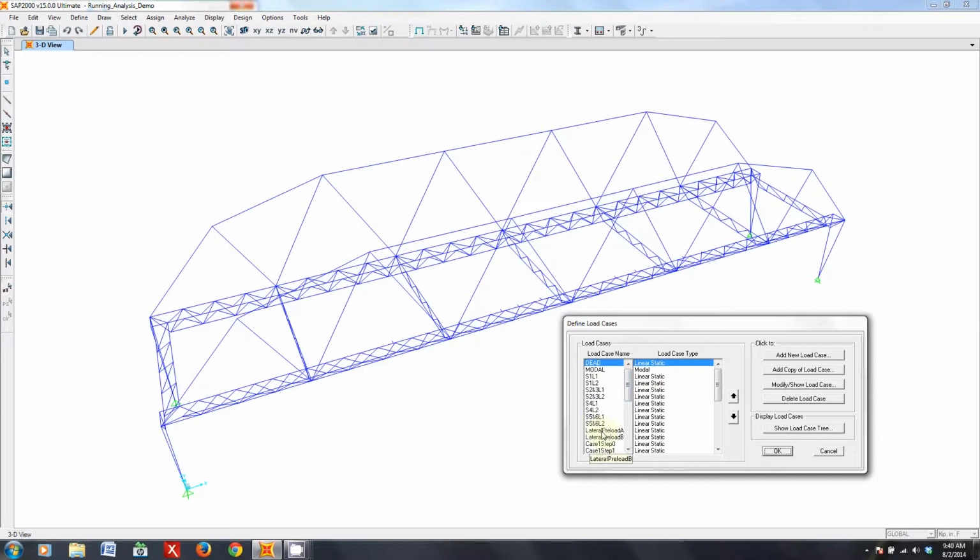I've also included preloads due to the lateral load, so you need preloads on both decking support surfaces in order to perform the preload. You can't see it here, but there's a lateral pull also, and that's that point load. And then I have all my load cases and all of the corresponding steps for each load case. Step number 0 corresponds to the preload. Step number 1 corresponds to the loading applied at load location 1, and step 2 corresponds to the loading placed on both load location 1 and 2.